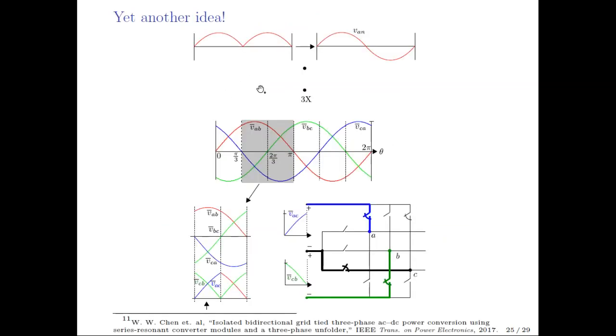There is another interesting idea I just want to mention here. Till now, what we have seen, we have 3 pulsating DC links for 3 phases. In the pulsating DC links, we have pulse width modulated DC voltages, where the average is this rectified sinusoid. Then after the DC link, we are using a line frequency switched H-bridge to generate the line cycle AC. So for 3 phases, these rectified line voltages are phase shifted. So we need 3 such DC links to generate 3 phase waveforms. Can we reduce the number of DC links?